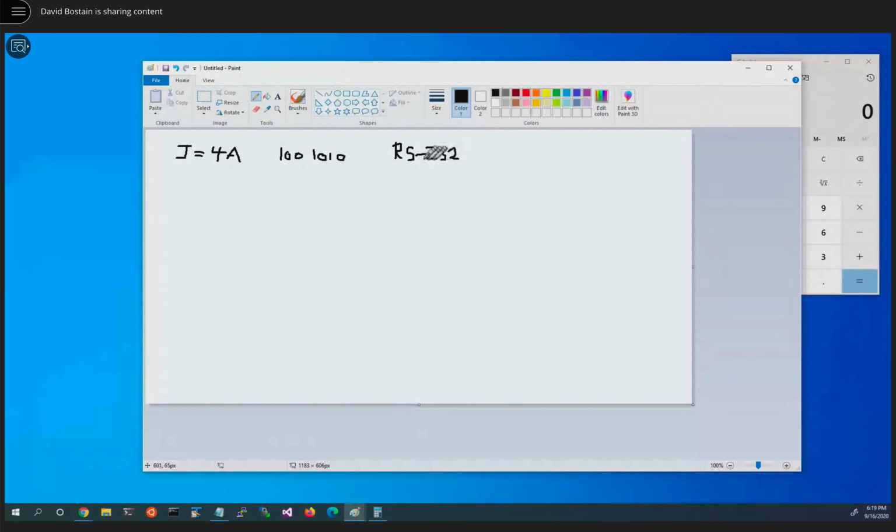Now, it allows us to make the decisions that we needed to make. For example, if we agree, for instance, we're going to send at 1200 bits per second, and we're going to send 7 data bits, we're going to send no parity bits, which is basically what? Parity none. And we're going to send 1 stop bit. The 2 ends can agree to follow that protocol.